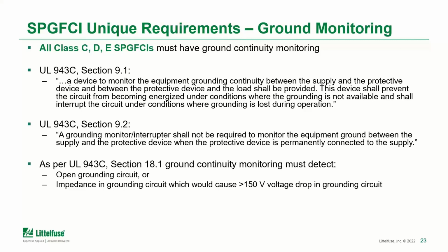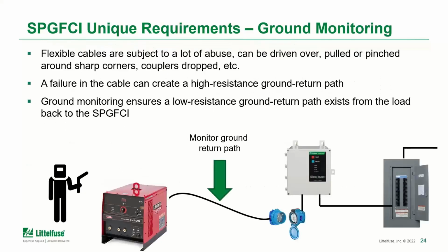So that is the ground from the load equipment back to the special purpose GFCI, and make sure that that grounding circuit is not open circuit. So the device has to actually de-energize if it senses an open circuit there, as well as a high impedance circuit that could cause an unsafe voltage drop across the grounding circuit. So this is something that's mandatory for these special purpose GFCIs to do.